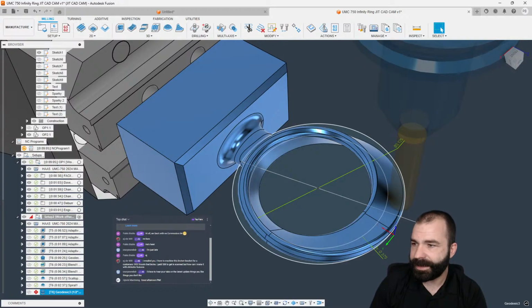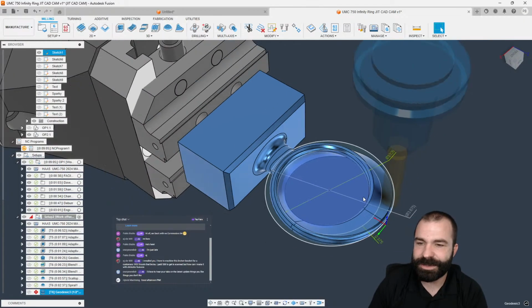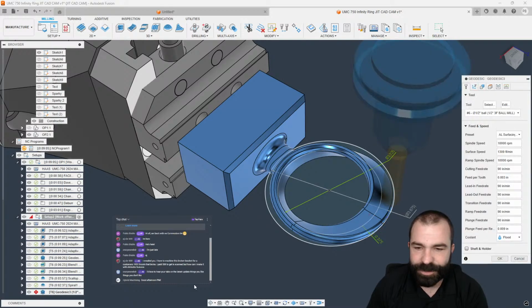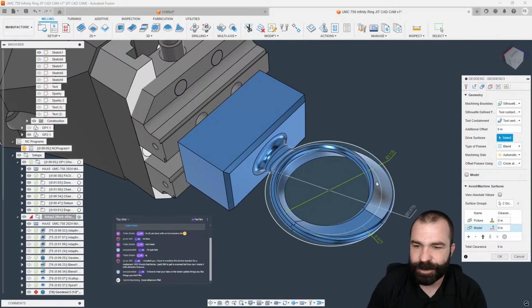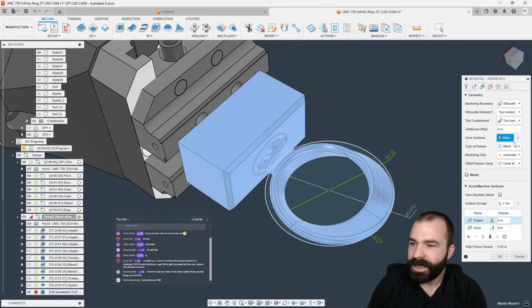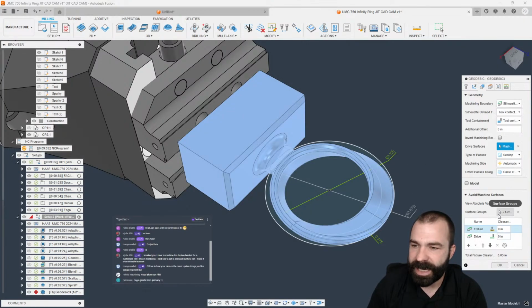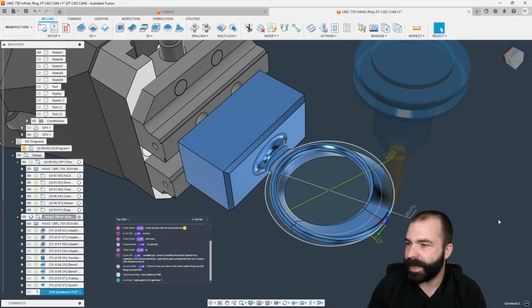I'm back. Hybrid machining, great to see you out there. So again, we got a failed toolpath. So with that geodesic, maybe we go ahead. Again, drive surface in this case was pulling the entire model. So again, we could go with a scallop strategy possibly. Again, circle at center. Let's go ahead and see what we get from that.